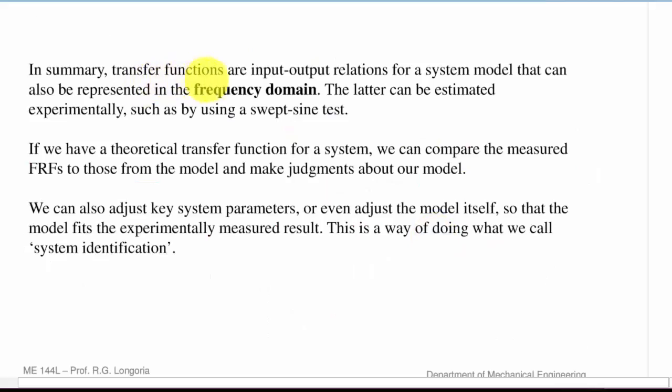So in summary, again, transfer functions are input-output relations for a system model that can also be represented in the frequency domain. The latter can be estimated experimentally, and that's what we're going to be doing in the lab using swept-sine testing. If we have a theoretical transfer function, we can compare the measured to the model and make judgments about our model, or we can also adjust key system parameters and adjust the model so that the model better fits what we measure. This is a way of doing what we call system identification.